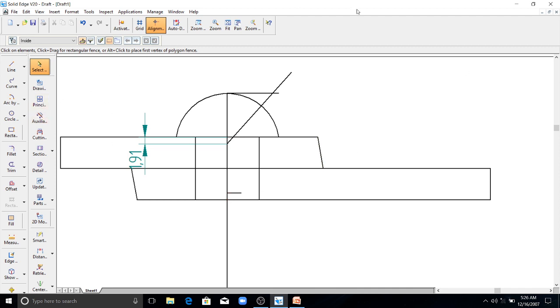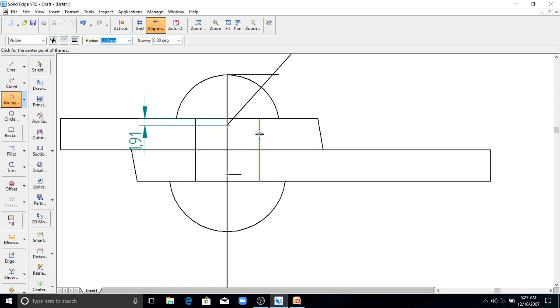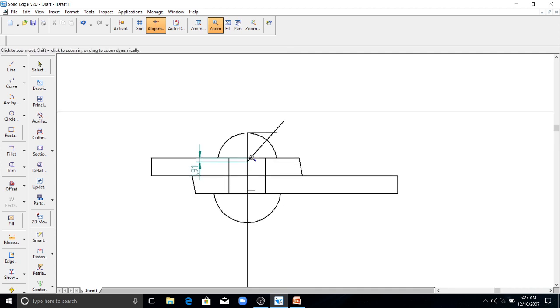So now you got the new radius from this center, with this as a center and the radius equal to 0.8 d, that will be 14.4 mm. So you have to maintain a 14.4 mm radius here to draw an arc. That will become the bottom portion of the rivet head. This is about the front view. Now you can remove this.